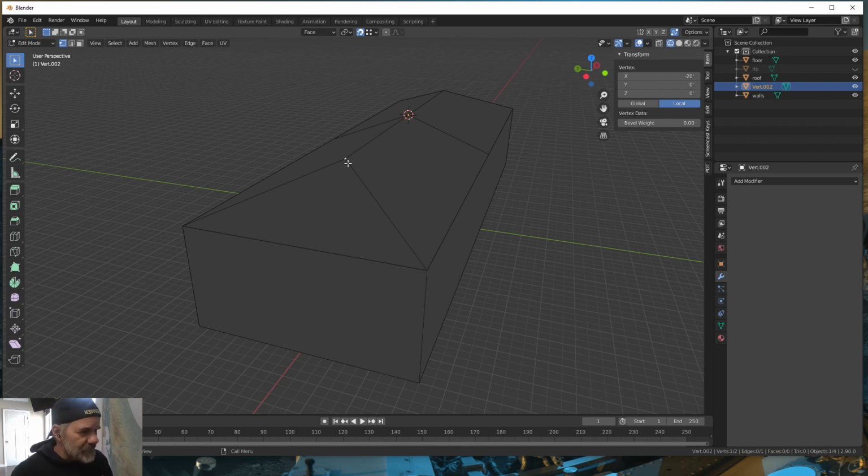All right, so anyway, we're creating a rib for the north and for the west and east face of our roof. So with this vertice selected, let me make sure I have that. Okay. All right, with this vertice selected, we're going to extrude that in the X direction. Oh, wait a minute. No, I'm not. I need to turn on my edge select because I don't have a vertice down here. Now with that selected, extrude X goes down my roof, snap to that line.